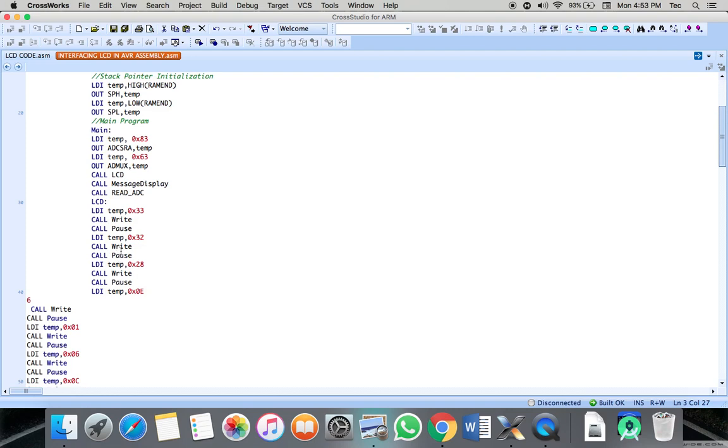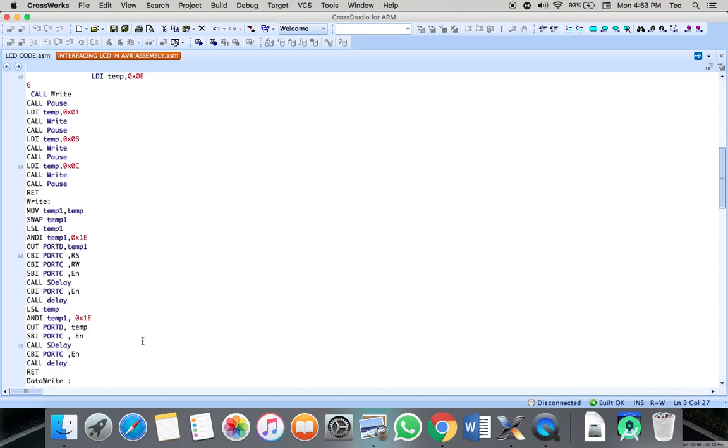And then what you're doing here is now you're instructing how the LCD is going to be writing those characters on the screen and what interval it will be waiting. So we now come here. You see under here, what we actually have is the label called write. So on the label that we are calling write, what's happening under write is that we call a pause.